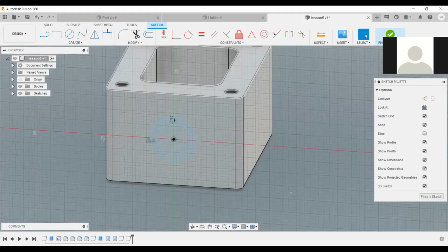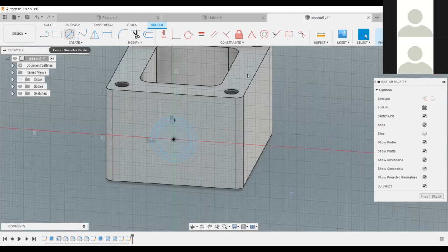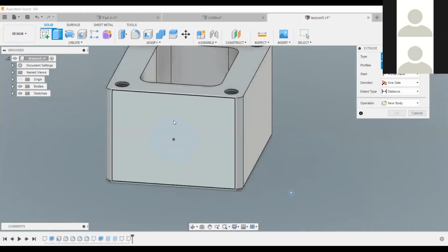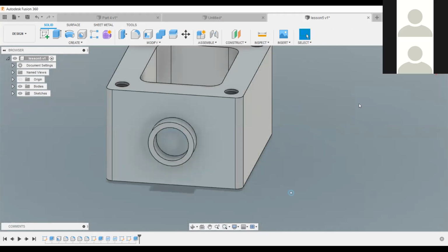So mine has offset. Yours has offset. Okay. Yeah. Good. Excuse me. Yes, sir. I think if you press S for the search tool, then you go to offset. You select offset faces. If you press S, then you go to the search tool.